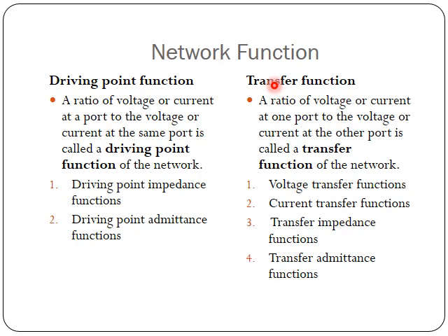Now let us see through the definition of these. A ratio of voltage or current at a port to the voltage or current at the same port is called a driving point function. Now a ratio of voltage or current at one port to the voltage or current at the other port, where these two quantities, the numerator and denominator, are from two different ports, is called a transfer function.